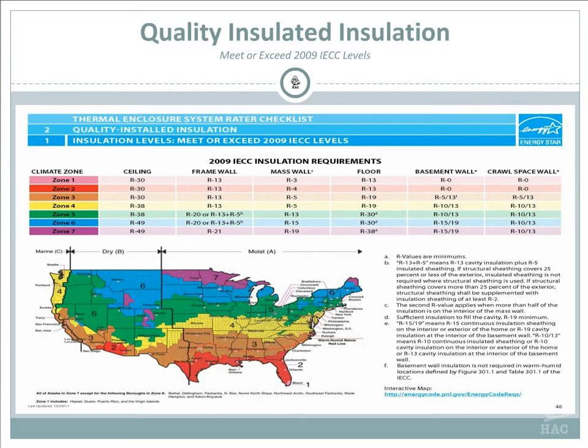One of the words you need to remember when you're doing attic or any kind of insulation is continuous, or continuously, because that's where they get you on a continuously insulated attic. They want that insulation to be the same R value over the side walls as it is in the middle. So in order to get that, you have to go into a different framing, and we'll talk about framing a little bit later on.